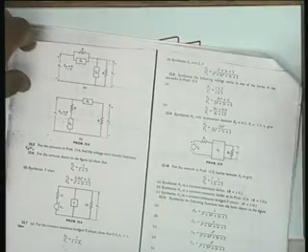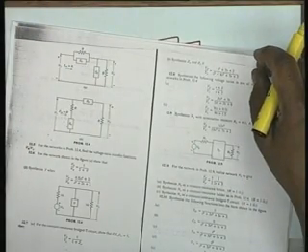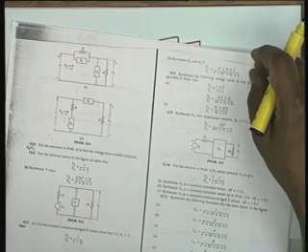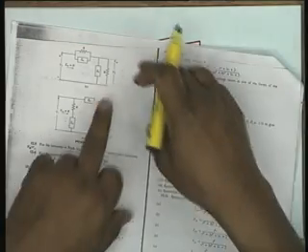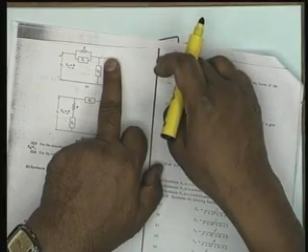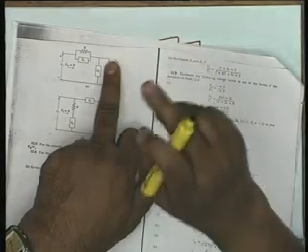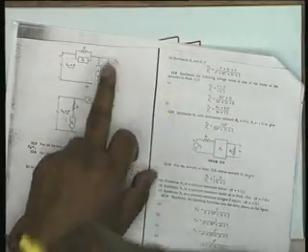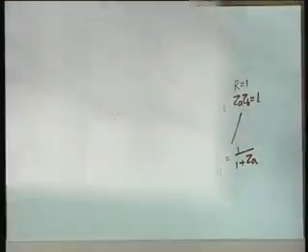Yes, sir. So you can make cascades of this. Again, we need to have that network in parallel with ZA also. Right. You use another network, R, ZA1, then ZB1, such that ZA1 and ZB1 multiplied again gives R squared. Okay, can we go back to this question?